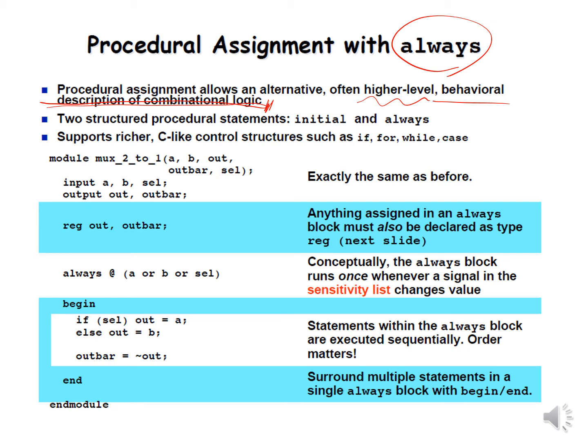There are two structured procedural statements, initial and always. The initial statement just provides the initial condition for any variable, but the always statement is what we typically use for actual logic design.